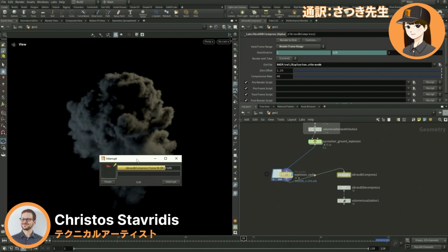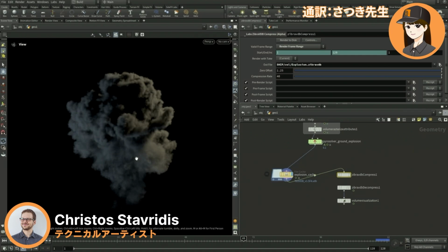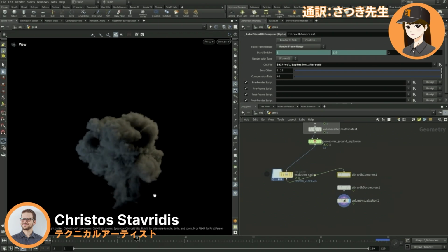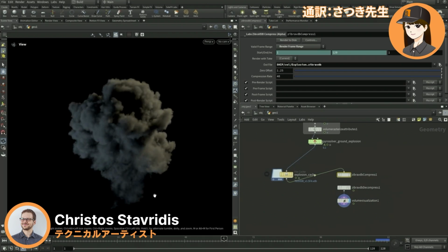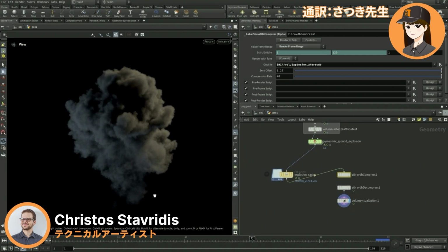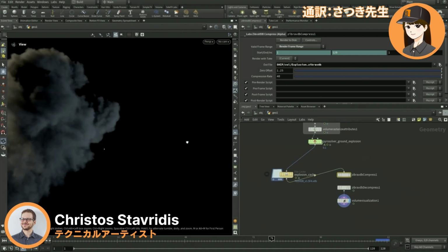The compression technology was first developed for the Unreal plugin. And before the Houdini plugin, you would have to make the compression inside Unreal. Now you can do this inside of Houdini, so you are caching a smaller file, and then you decompress in Unreal Engine. The decompress node will load that single file and put it on the GPU, so we get rid of the input-output problem.